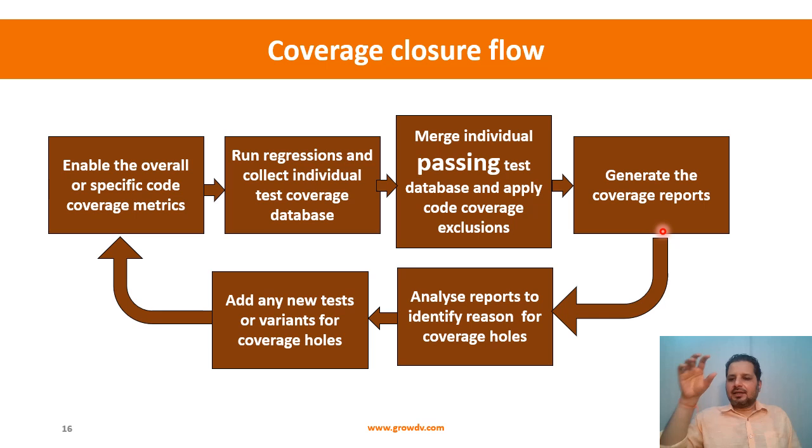You can go there, and then per module level what are those metrics, and then you go deeper into another module, like that module might be instancing lower leaf level modules. You can go to those leaf level modules and look at what these n number of metrics are, right? The code coverage metrics I'm talking about, because code coverage is implementation specific, so it follows the RTL structure from your top level module to the modules present within that. It will show you at that particular module level what's the line coverage, branch coverage, expression coverage, FEC coverage, everything. It will show you the overall number as well as the breakup, and then you can click on those numbers and it will further show you within that particular module.